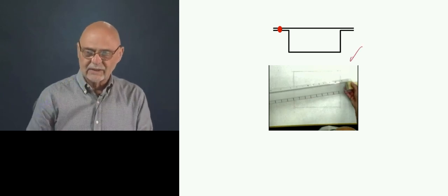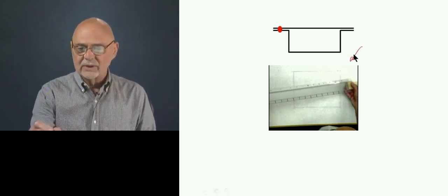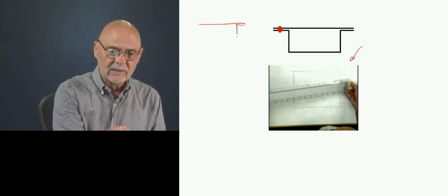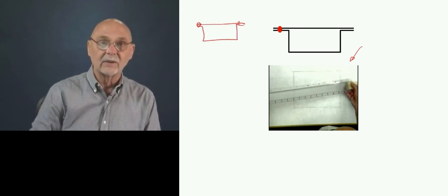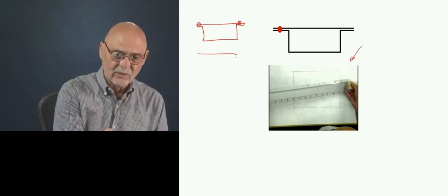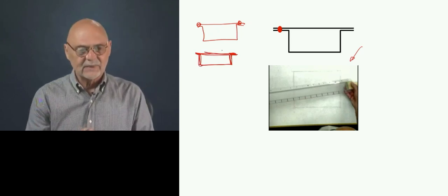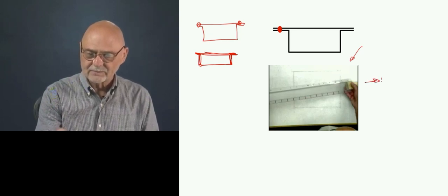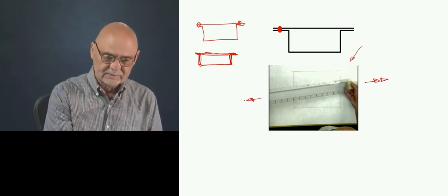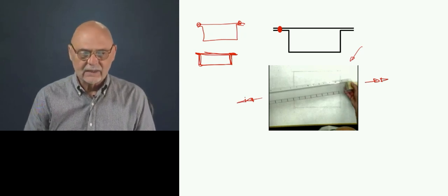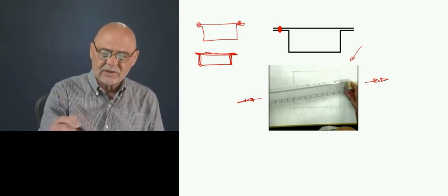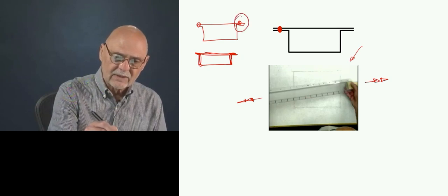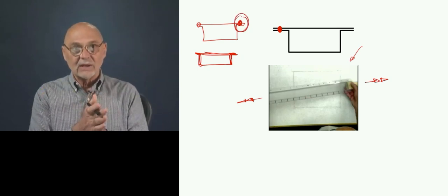So what I'm going to show you here is a beam that we would normally say is going to be welded together here and here. So effectively, in what we've looked at before, we wouldn't even show the spot welds, right? We would just have something like this. And if we're twisting it, in this case, we're going to apply a torque here and here. And what we're going to show is what is the motion that this row of spot welds is really restraining.